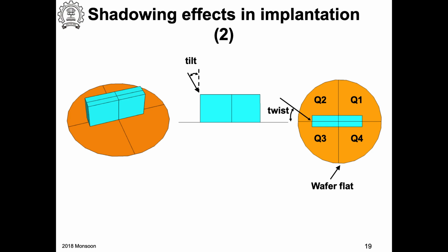So the gate will be on top like this, and this would be my source. This would be the drain. So what about the sides? Because this is my source, and I implant it only from the top. I need to get the dopants deep down till this point, so I need to use a very high energy. But still I will not get a uniform profile.